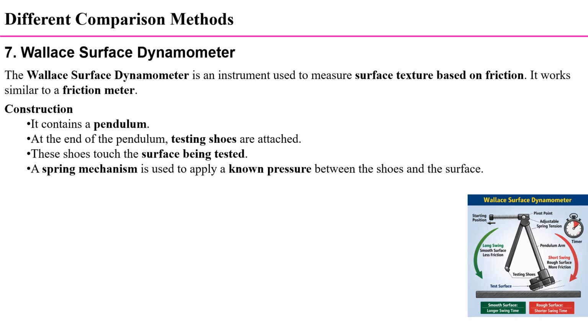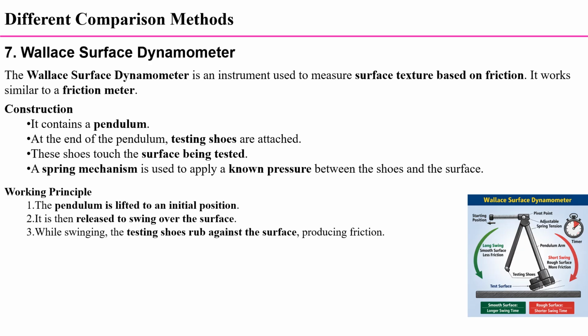It contains a pendulum, and at the end of the pendulum, testing shoes are attached. These shoes touch the surface being tested, and a spring mechanism is used to apply a known pressure between the shoes and the surface. So let's see the working principle.